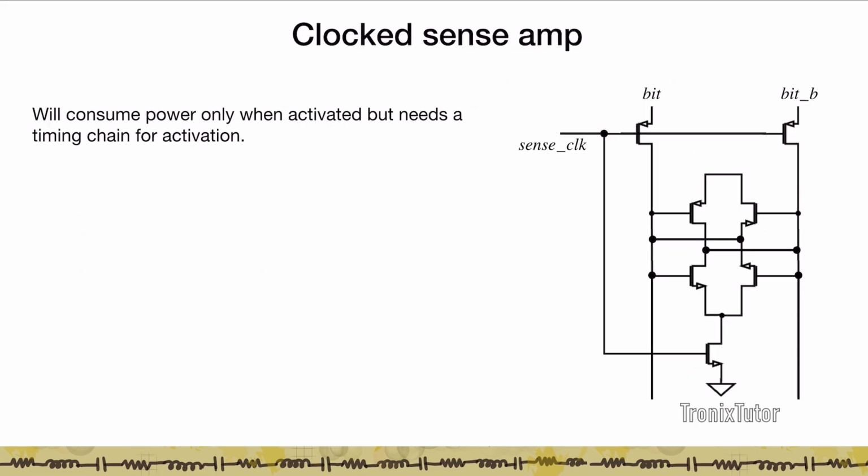So what we do typically, because here we are sensing only 0 and 1, we don't really care about small signal. What we do is we sometimes use a clocked sense amp, which again consists of back-to-back connected inverters. The back-to-back connected inverter is a circuit we know which can quickly flip from 1 to 0 depending on the noise associated with that particular node.